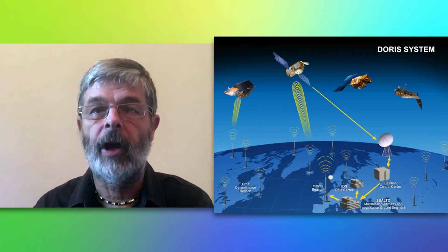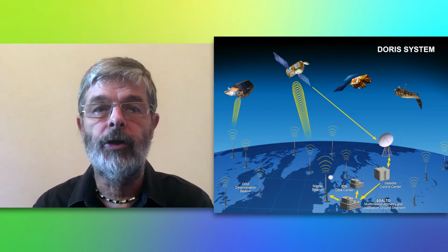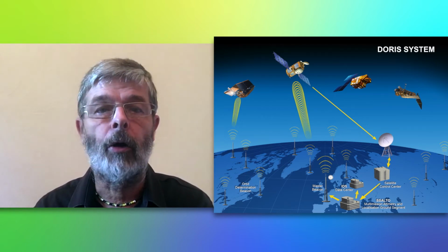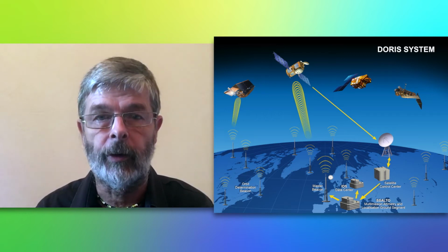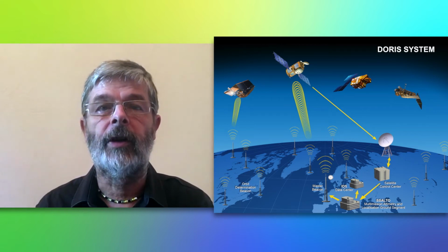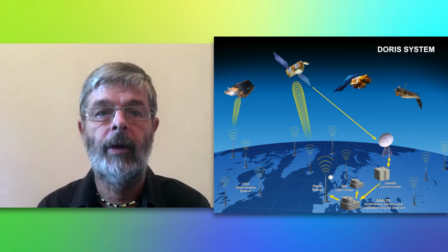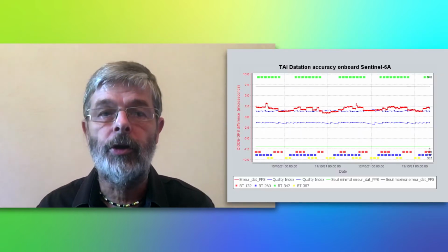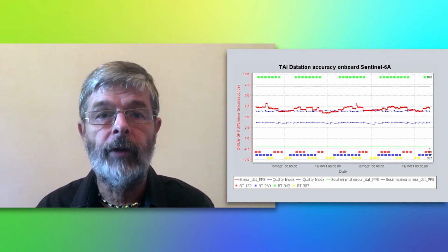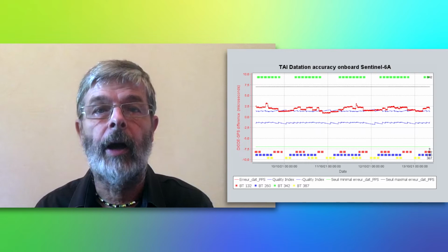Their transmission time, or time tag, is accurately known in ground time. During each satellite pass, the time beacon's signals are also precisely time-tagged by the Doris internal clock, an ultra-stable oscillator, and a simple time transfer technique gives the correspondence between the onboard clock and ground atomic time. Using this, each Doris receiver is able, for each onboard event, a time tick, to give its value in international atomic time. Doris brings TAI to the spacecraft.